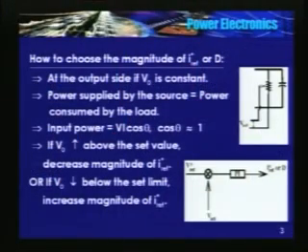the capacitor voltage will also have a second harmonic component. Remember, it has a second harmonic component. So the capacitor voltage will have a second order harmonic component. It is not constant, even if the source current is a sinusoid. What happens in the three phase case we will see when we discuss the three phase converter.